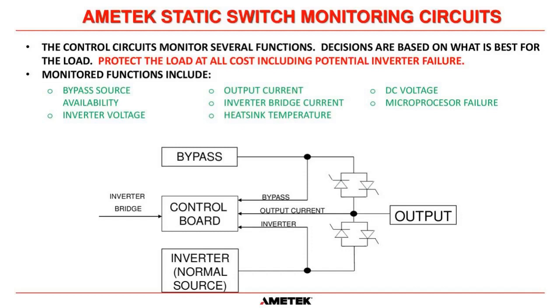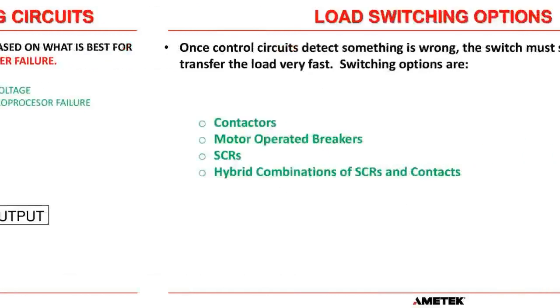And again, all the decision process is protect the load at all costs. Avoid ever dropping the load, including potential inverter failure. We may risk inverter failure if we have to avoid dropping the load. You can rebuild an inverter a lot less expensive than restarting a plant. Okay?